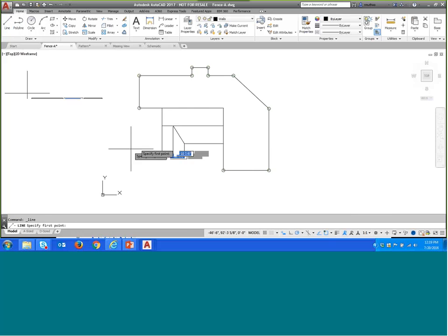And then see the drawing, go here and choose this, and then here you go, the extension. But I want the extension from this endpoint as well. So it just goes and snaps to that location. See, it chooses the right endpoint, and it chooses the bottom endpoint, and then it snaps to the intersection there, and that's it. So that's how we can snap accurately and precisely to different object snaps that we have set from the list here.